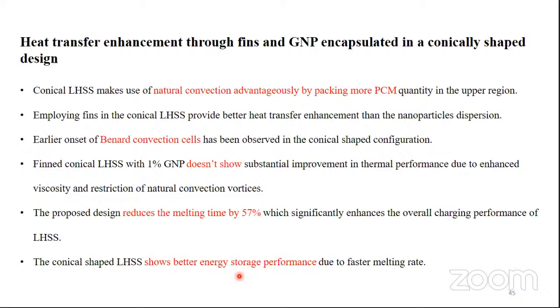Now, finned conical latent heat storage system with 1% GNP, it is having a negative enhancement ratio, if you remember. So it does not show any substantial improvement in the thermal performance due to the enhanced viscosity.